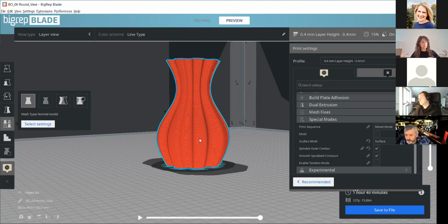But if you have something like a vase or something you're able to flip down, it also obviously can't overextend that 45-degree angle. So this angle is okay. If it starts to bend a little bit further, you're probably going to have some hanging or some holes in your model, because essentially only having one loop, there's not 2 loops for it to adhere to, sort of allowing for that angle to happen.